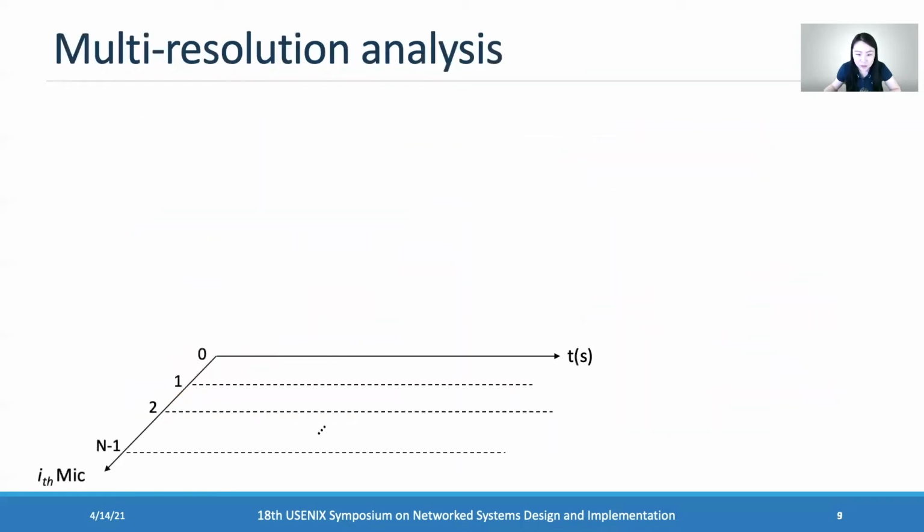We propose multi-resolution analysis to reduce coherence. Suppose we have n microphones, and the phase difference along these time series signals encodes the spatial relationship. One straightforward idea to separate multipaths is to align and cancel paths along the time dimension. But it's hard to align the initial ramping up signals, and the cancellation is not accurate.